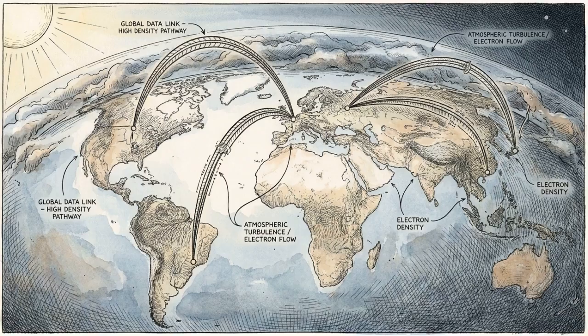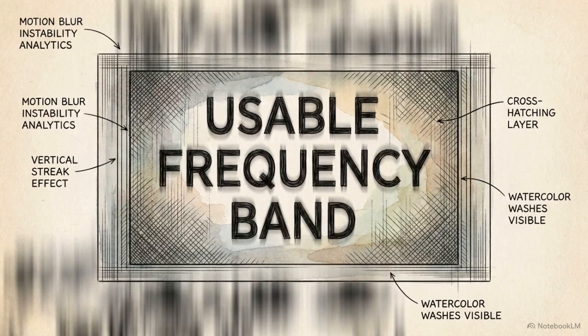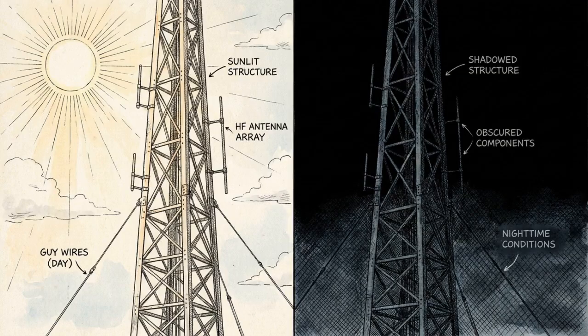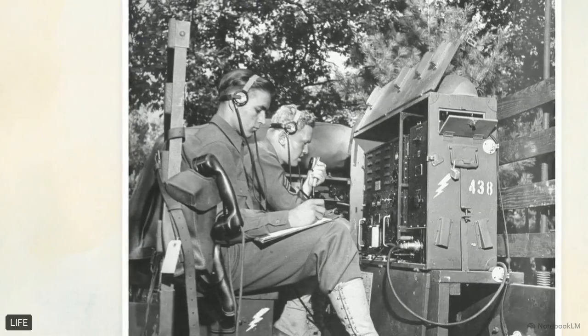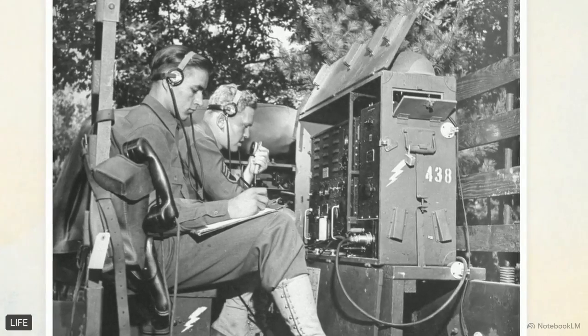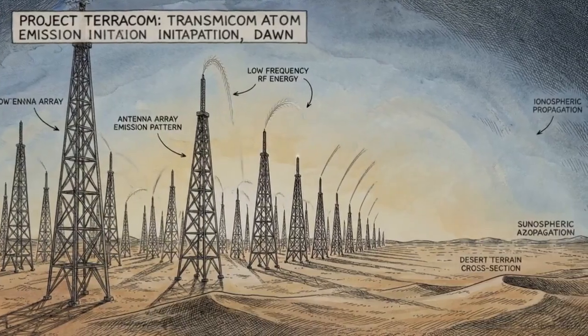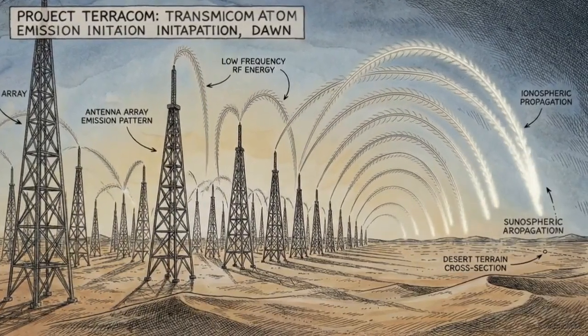The ionosphere remains a volatile medium that must be actively navigated to enable long-distance communication. Transmission requires a frequency high enough to minimize absorption in the dense D layer, but low enough to ensure the F layer can still pivot the wave back to Earth. This operational window is constantly moving, influenced by diurnal shifts, the equatorial fountains, and auroral disturbances. Operators maintain the link by dynamically adjusting frequency and power to match the shifting currents of the atmosphere. Global high-frequency communication relies on the continuous, real-time synchronization of transmission parameters with the fluctuating properties of the ionospheric plasma.